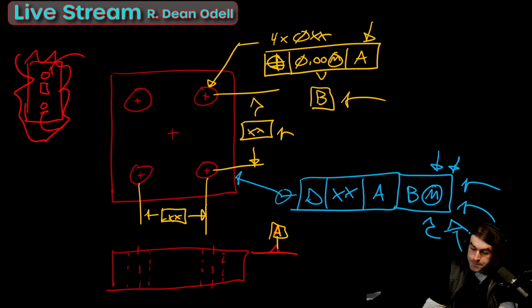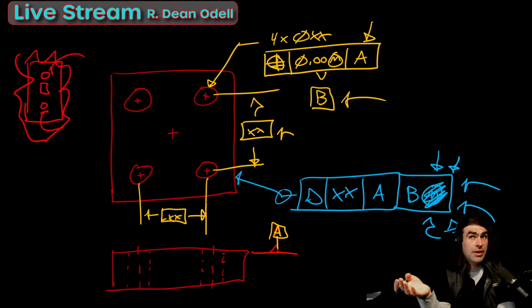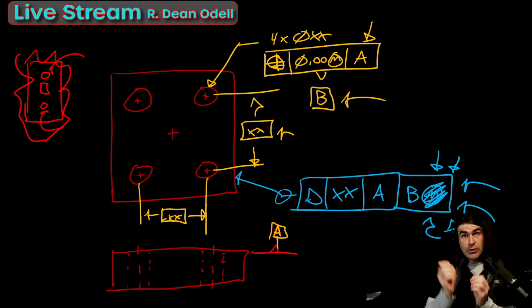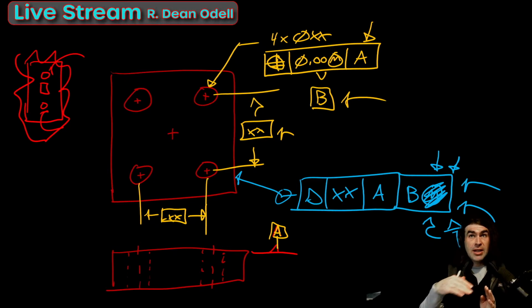What you're asking for, if you send this as RMB, regardless of material boundary, right? You've got a pattern of features of size. What that means is that when you simulate it, you have to have 4 perfect, true geometric counterparts, right? They're perpendicular to datum A, and they all expand simultaneously, perfectly, until the part is captured, right? So imagine 4 expanding pins that expand until the part fits, and then you take your measurements from the center of that. It's very difficult to do practically.